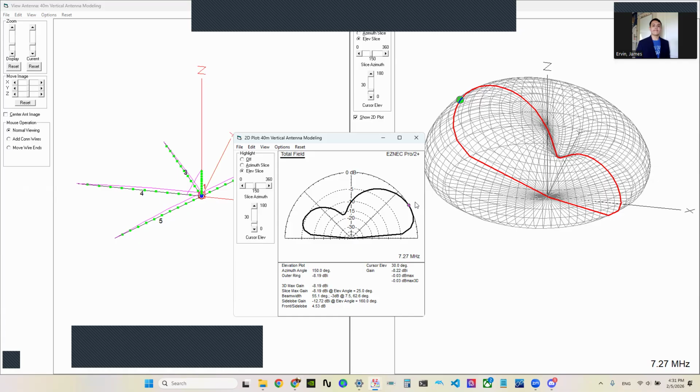So one thing you're going to want to consider when you're designing antennas is if it's not terribly efficient, you may want to not run full power into it, because you may just be building a dummy load where you give off all your power as heat. And I don't know about y'all, but melting wires and melting capacitors and melting insulation, not the best time known to man. So yeah, the other cool thing about having our elevation slices is we can see a front to back ratio.